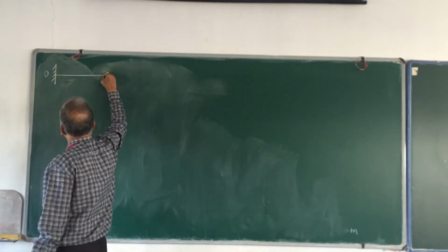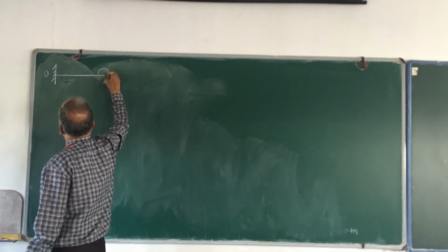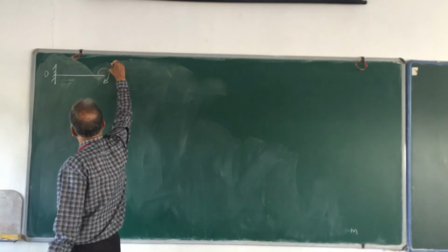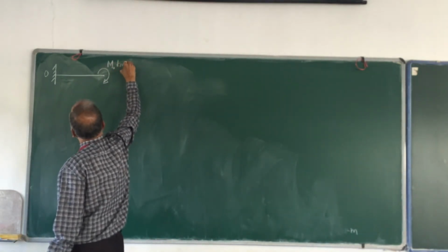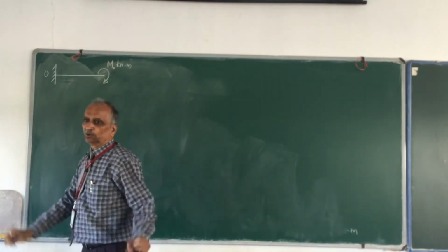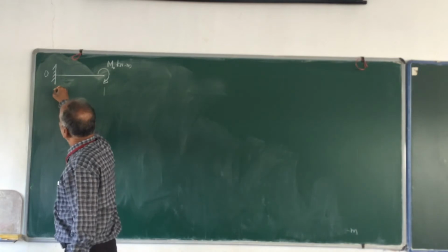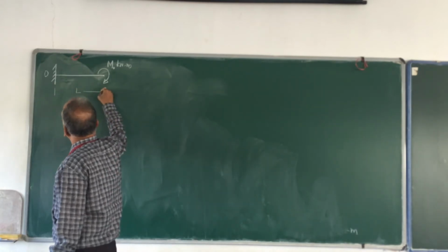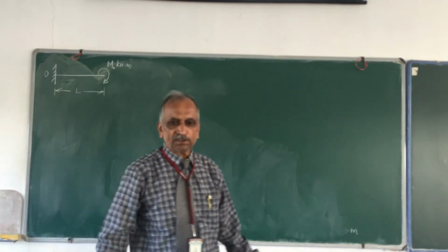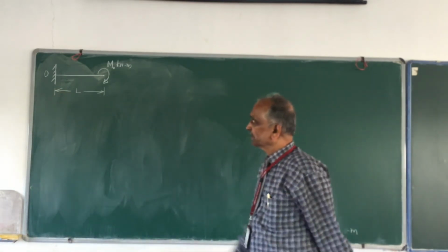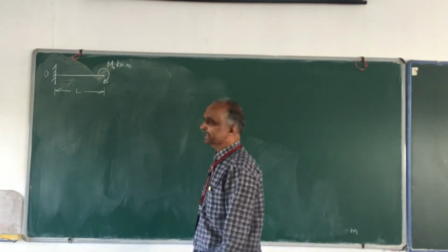Then I am applying a load. This is the moment, m naught kilonewton meter. This is known to me, and the length of this is say L. L is the length. So this is all I know. Now for this, draw the bending moment diagram and shear force diagram.